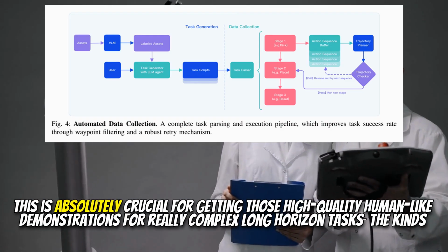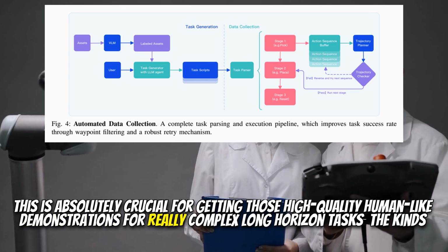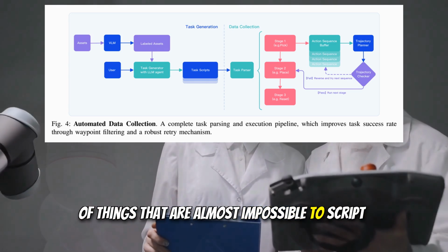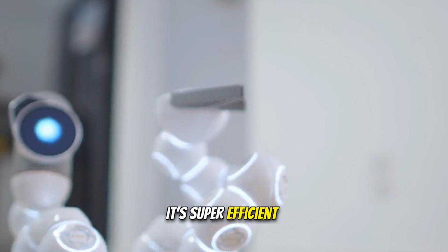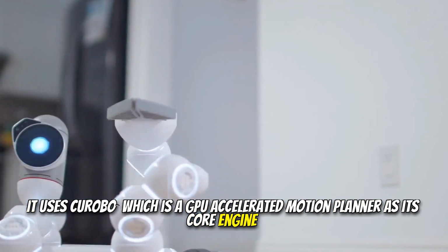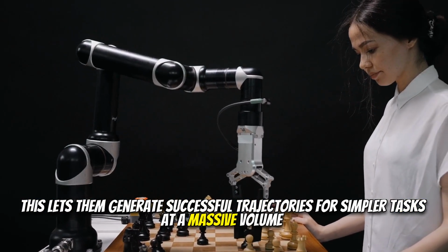This is absolutely crucial for getting those high-quality, human-like demonstrations for really complex, long-horizon tasks, the kinds of things that are almost impossible to script. And then the second mode is where the automation and the real scale comes from. That's the automated collection. It's super efficient. It uses cuRobo, which is a GPU-accelerated motion planner, as its core engine. This lets them generate successful trajectories for simpler tasks at a massive volume.